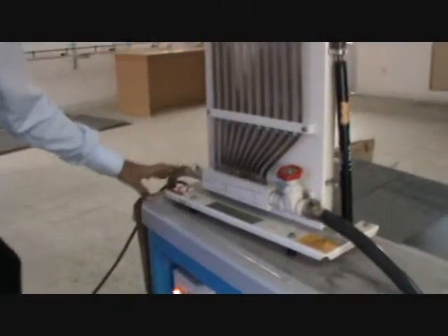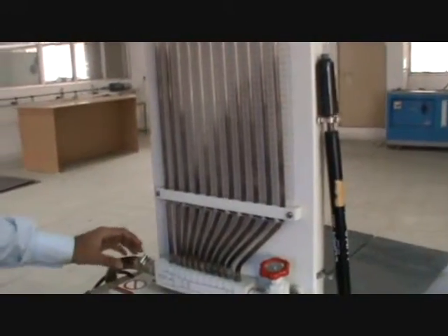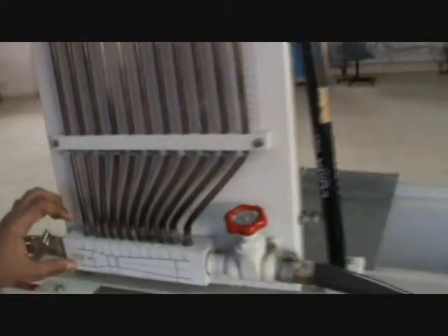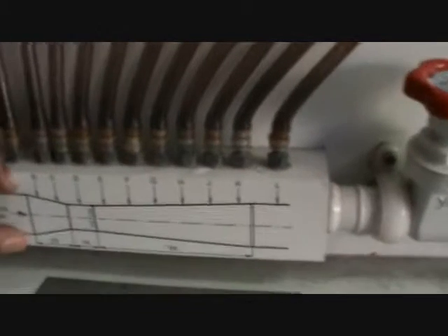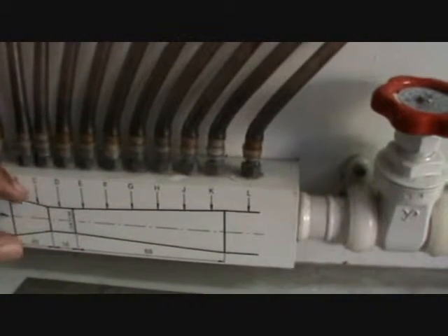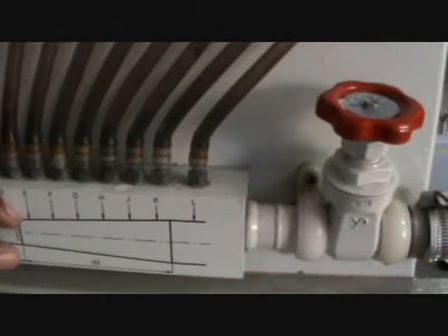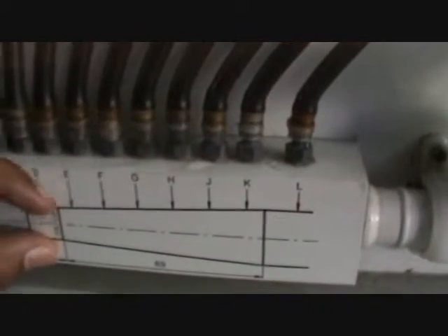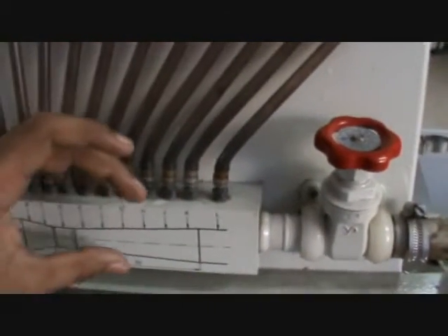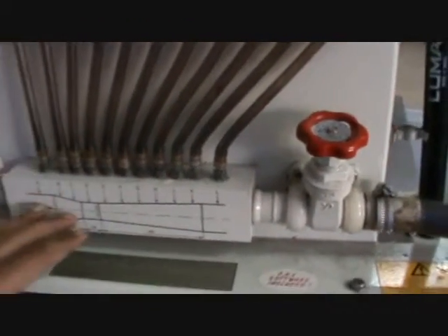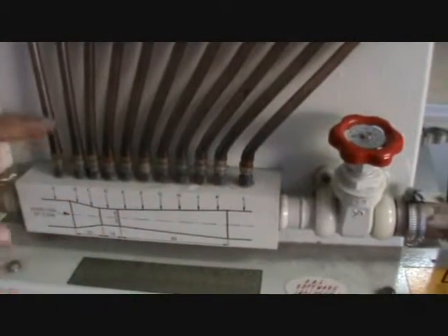Start this switch, and then this switch, so that the pump can start. Then water from the pump will come through this section to the venturimeter. This is the inlet section, then the convergent section. Inside this, velocity will increase so that the pressure will decrease. Then the throat section, where velocity and pressure remain constant. Then the divergent section, where velocity will decrease and pressure will increase. So pressure variation along the length of the venturimeter can be recorded by seeing the height of water column through these manometers. Here we can see the height of water column at this section, and this section.